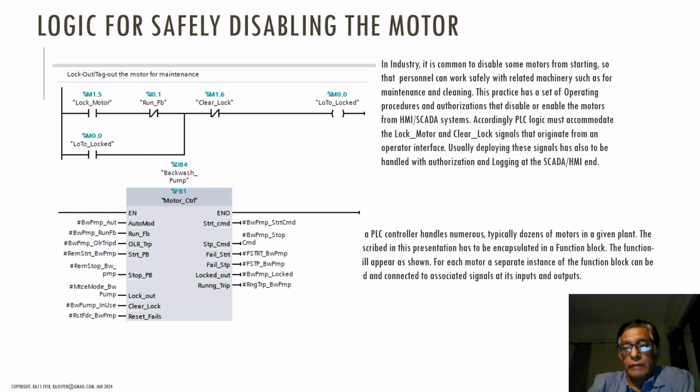Now, having correctly configured logic and ensured that you got the common alarm signals, you have one more signal you have to arrange. That is, you have to inhibit starting of the feeder motor for safety, and this is necessary from SCADA also for logging. You see, in certain large plants, there are large vessels with agitators inside and all.